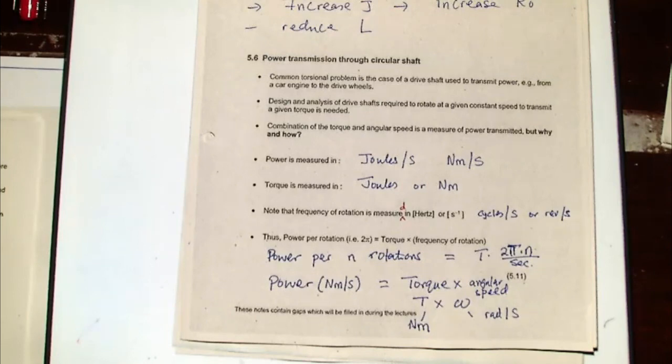So if you look at the example of the car, the power coming from the main engine does not change. So when you change the gear, you are changing the speed through your gear change. And by changing that speed, you therefore have a different torque. So at low gear, when your speed is very low, the torque is very high because the power doesn't change. And at high gear, when your speed is very high, the torque is quite low.